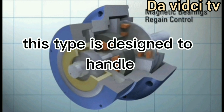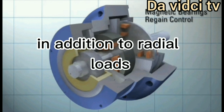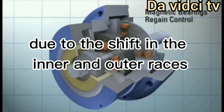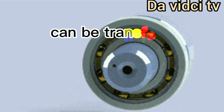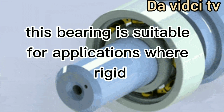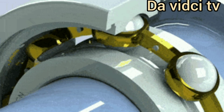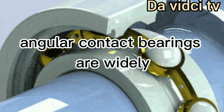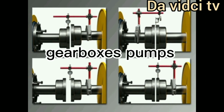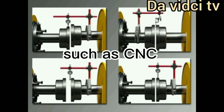This type is designed to handle greater amounts of axial loads in both directions in addition to radial loads. Due to the shift in the inner and outer races, the axial load can be transferred through the bearing to the housing. This bearing is suitable for applications where rigid axial guidance is required.